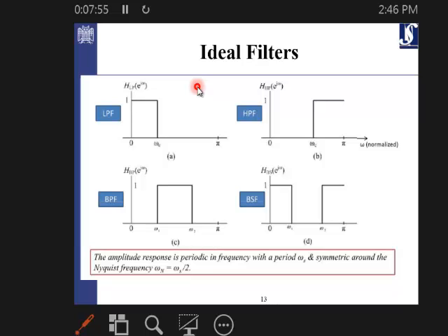In my case, I'm talking loudly, so I'm not talking in a normal way. If I talk, for example, in a normal way or very slowly, then you might not hear that, and it's because of SNR, the signal to noise ratio. Whenever we have noise anywhere, one of the most important measures that you have to mention is the amount of SNR. How much SNR we have. Normally for people, if the signal to noise ratio is more than 20 dB, you know already the scaling of dB is a logarithmic scaling, if it's more than 20 dB, you can ignore the noise.